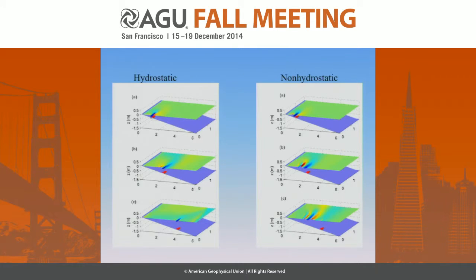This is essentially just a picture of that same event evolving spatially, and you can also see that as the non-hydrostatic or dispersive solution evolves, it's also more able to diffract to the sides and evolve in a more two-dimensional pattern spatially. So the hydrostatic and the non-hydrostatic simulations are very, very different, even though we tend to think of tsunami motions as occurring basically in fairly shallow water.